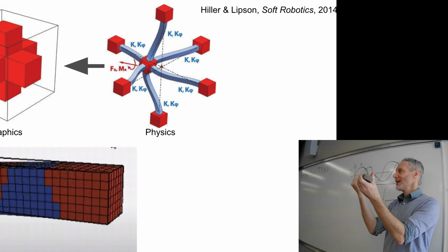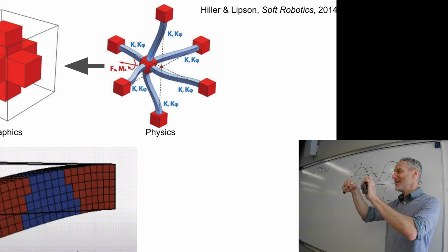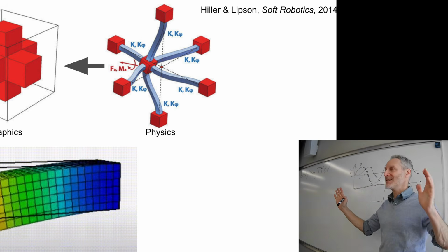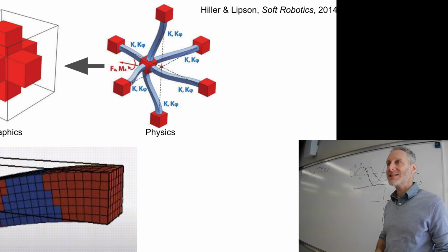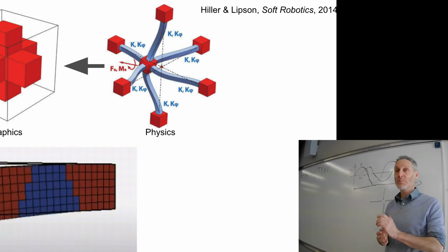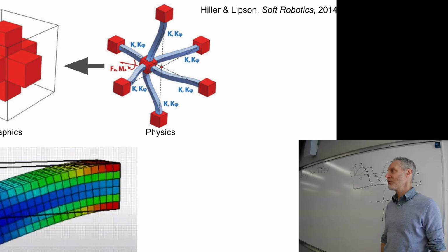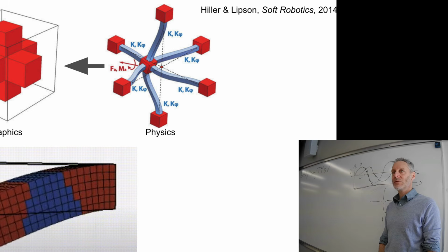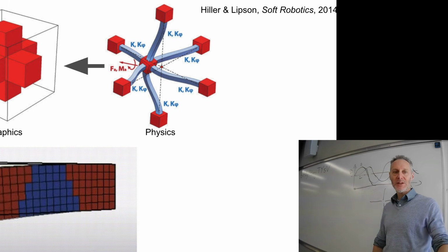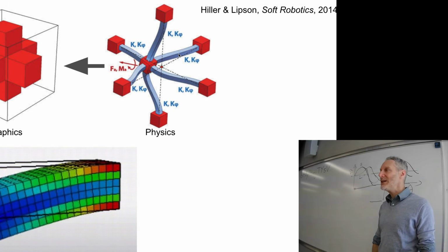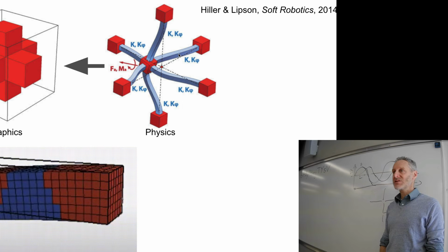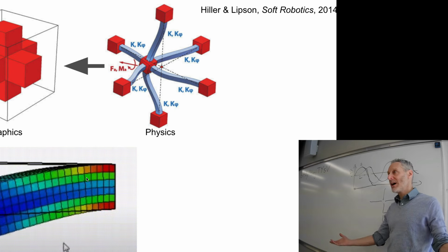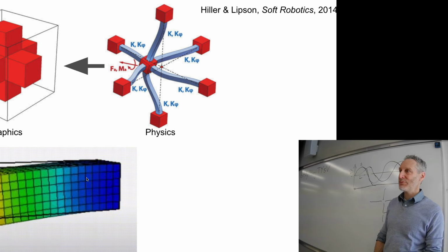I can never do this. Yeah, you know what I mean. You can twist it in 3 different directions. So all 6 of those numbers taken together is going to dictate how stiff or soft this beam is along those 6 different ways of pushing or pulling or twisting the beam. So far, so good? As you can see from this picture, every individual beam can have its own set of stiffnesses. You can make a composite of a whole bunch of beams stuck together that are stiff or soft in different ways.